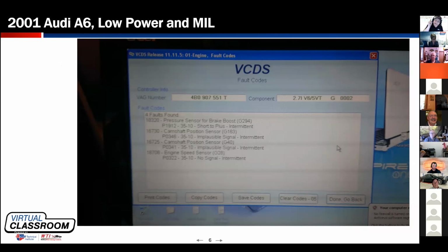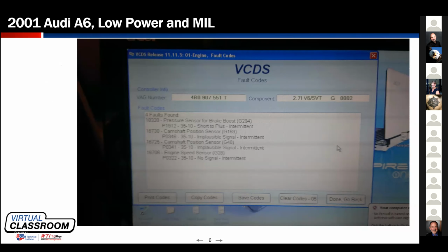Now, look, I'll go ahead and apologize for the quality of the picture I put on your screen, because frankly, this was just a car I diagnosed. I didn't plan on turning it into a case study, but it backs this up perfectly. We're looking at a 2001 Audi A6. This is a 2.8 liter V6, naturally aspirated, all-wheel drive automatic car. The small story behind it is that this vehicle broke a timing belt and bent some valves. Those of you with some knowledge of this platform realize they run 5 valves per cylinder, and it's a lot of damage when that happens.